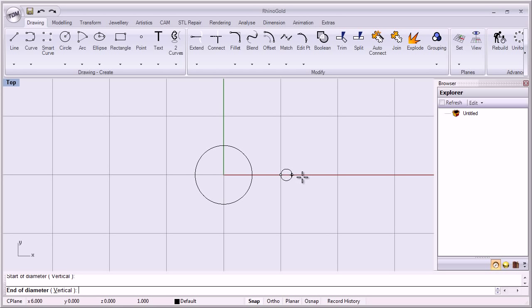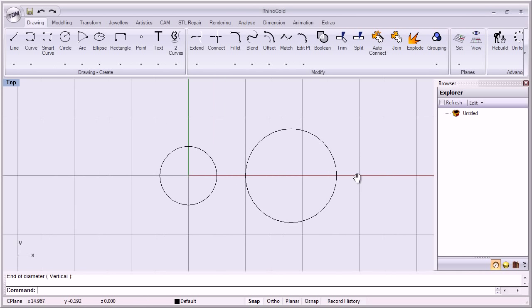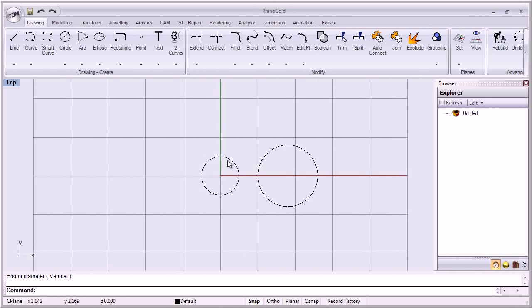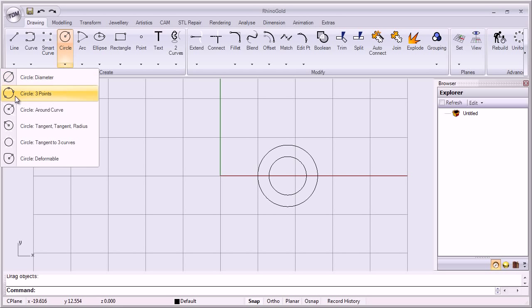For the end of the diameter we can introduce any number that we want our diameter to be, for example 8, clicking enter. Now I just have to place the final point of my circle, and I know that it's 8 m of diameter. I'm going to place my second point here, for example, it doesn't matter. Okay, well done.